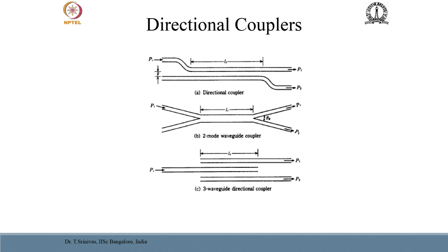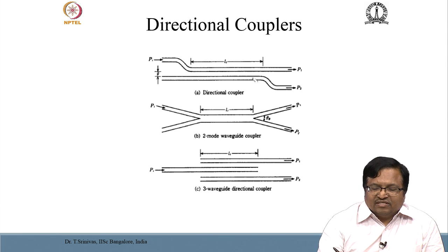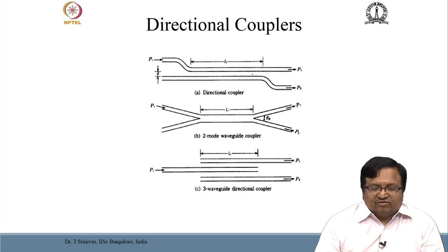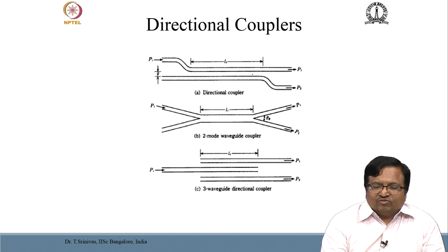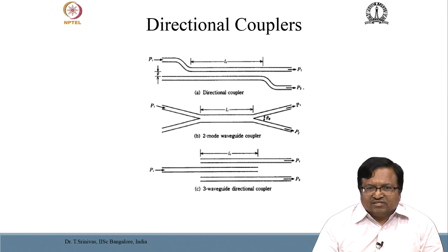In the beginning we have seen a directional coupler where light could be exchanged from the input port to any of the output ports, with a higher refractive index region in the waveguides and a lower refractive index region in the intervening medium. So, we saw that the light could be tunneled from the input port to the opposite port. Directional couplers are very useful for many applications, for switching the power between different ports or redistribution and so on. A directional coupler is typically considered a multi-purpose device which can be configured for many purposes, in particular in association with electro-optic effects.